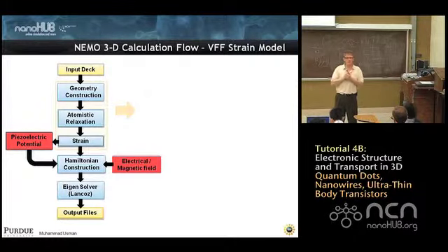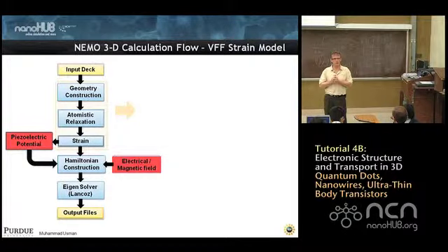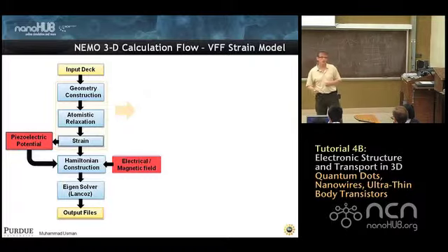It's sort of like a minimization problem where everybody naturally would like to lay at a certain distance from its neighbor, a particular neighbor, and the neighbor-neighbor interaction is different. For example, indium arsenide likes to be in a different bond length than gallium arsenide, but if you throw those guys together, they all argue with each other, no, I like to be here, and then you do a conjugate gradient minimization, and that is what this atomic relaxation does. Is there potential for finding the wrong minimization?